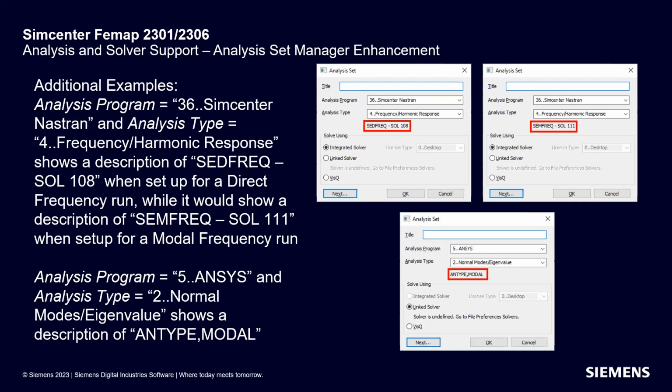I do not know if that can actually, well, I think if you have your enterprise Nastran set up to use tokens, it should certainly work. But as far as using tokens where you're using, say, the integrated version of Femap through the desktop to run, you cannot then have it use tokens to run an additional thing like super elements or aeroelasticity or anything. But again, if you have access to run it via enterprise Nastran, that should work by just pointing to that license server that's serving out the enterprise Nastran licenses or tokens.